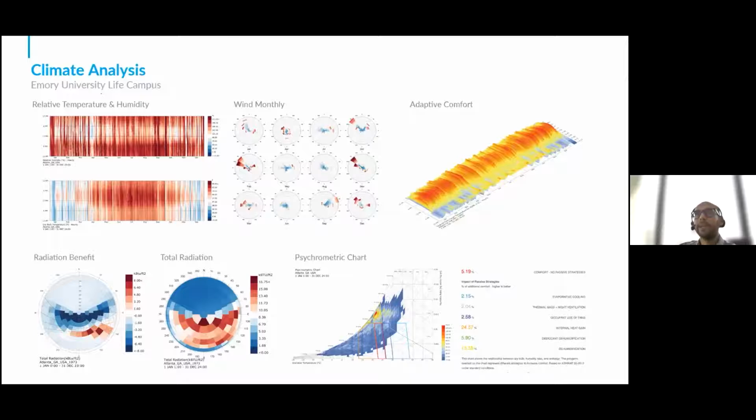Once we have covered all of those aspects is when we jump to the active side of things. That means now you'll start selecting different HVAC systems. You will talk about sizing those HVAC systems or having more efficient HVAC systems, implementing a couple of different strategies such as heat recovery or energy recovery and stuff like that. And once we have done all of these processes and we have optimized the EUI as much as we can, that's when we actually jump to the solar PVs or renewable energy side of things and say, how much of this EUI can be offset by using solar PVs or maybe some other renewable energy sources.